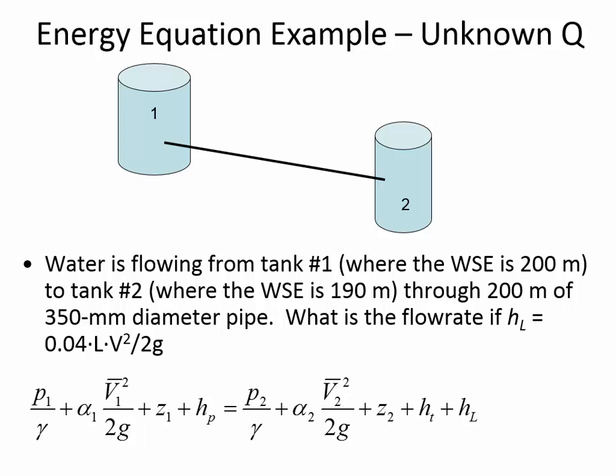Remember, as turbulent flow goes up, so does the energy loss associated with the turbulent flow. So this is basically conceptually saying the longer the pipe, the more head loss you'll have. The higher velocity leads to higher energy losses. And so we want to find out how fast is the water going to go through this system when we have the conditions that are specified.